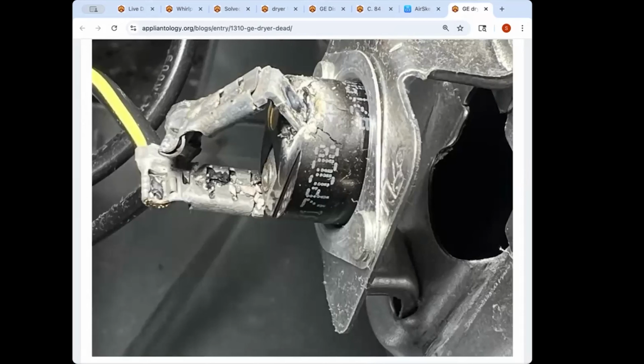wires don't really wear out, unless you have a bad connection. So would you say with all the amps going through this, like for Tim's, that was because of the amps, or was it because of the amps combined with maybe a poor connection? Well, the amps combined with a poor connection is what's going to give you your heat.